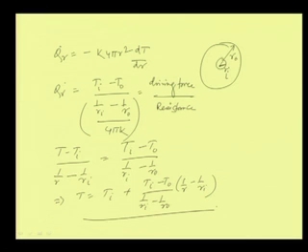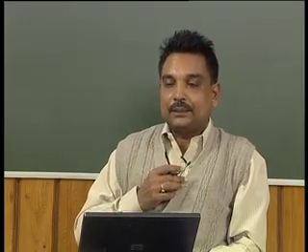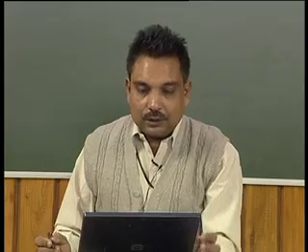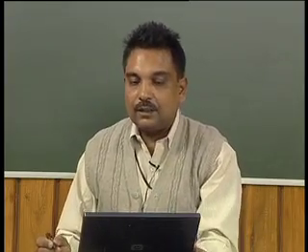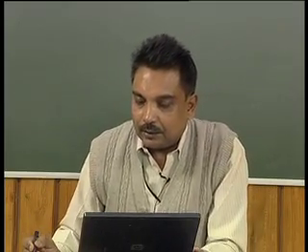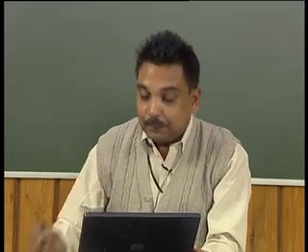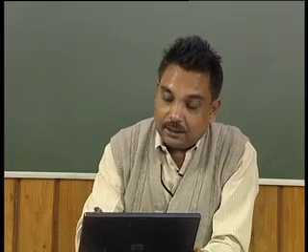Now, in case of a sphere, the temperature variation is again non-linear, not a linear variation like flow through a plane wall. Again, the reason is that the area is a continually increasing function as we go on increasing the radius of the sphere. The same expressions we can also calculate from the general conduction equation. But before we go to that part, we will see the electrical analogy again.